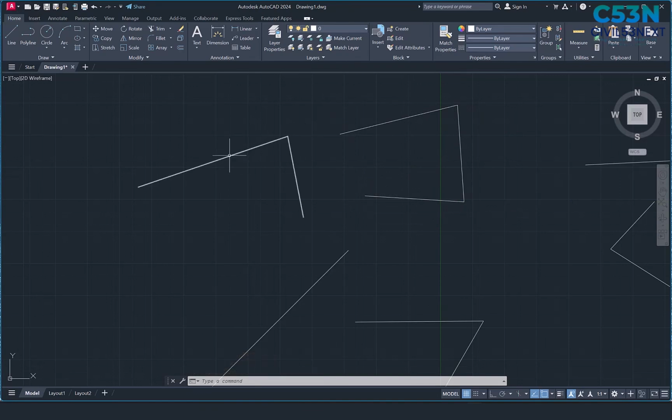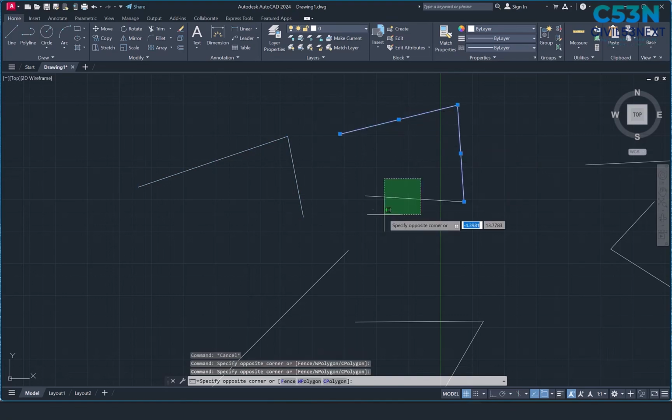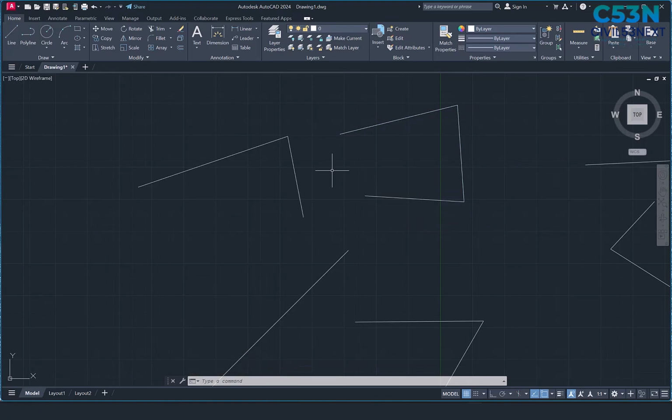And we draw this by PolyLine. So if we select this, it's going to be selected as one object since it's drawn by PolyLine. But for the line one, if you select it, it will be selected individually. So this is the difference between line and PolyLine command. The difference in short, PolyLine will be selected as one object and line is selected as individual members.